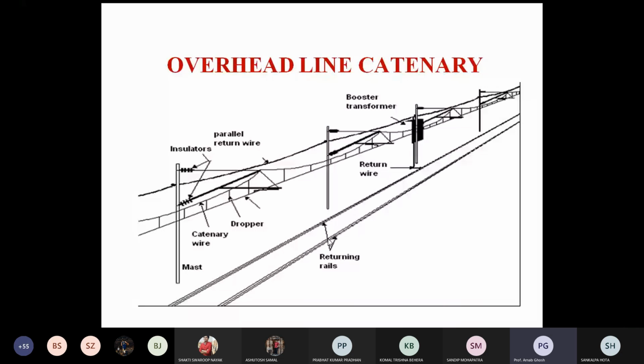After some time, you know that the railway path is also connected with the ground. It is not directly grounded; there is some earthing process. So how do you make the earthing? You have to dig one big hole. Then a huge earthing rod is there. You have to give some salt. Then you put in the earthing rod, and that big hole is poured with salt and everything, making that path minimal resistance.